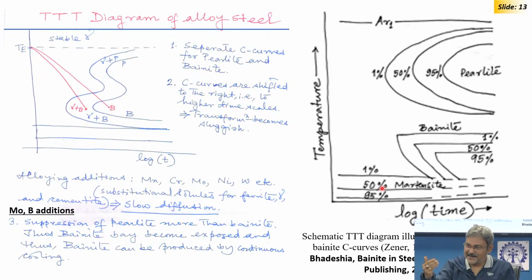So, there are martensitic transformations which are time dependent, shown in the papers, and movies are taken. But since this transformation happens very fast, the interface moves like a zip, you cannot appreciate the effect of the time. So, you only see the effect of temperature, which saturates a certain number of nuclei. Okay. If you reduce temperature, more nuclei will now activate, so you will say higher fraction of nucleation. That is why the bainite top curve is a flat curve like martensite start.